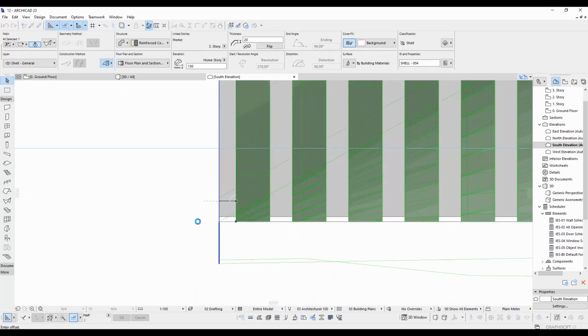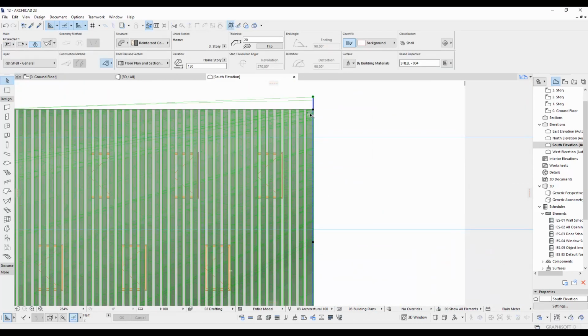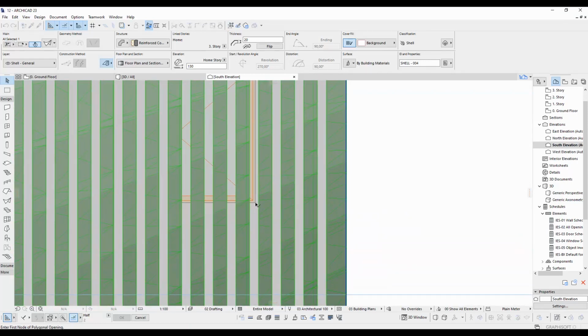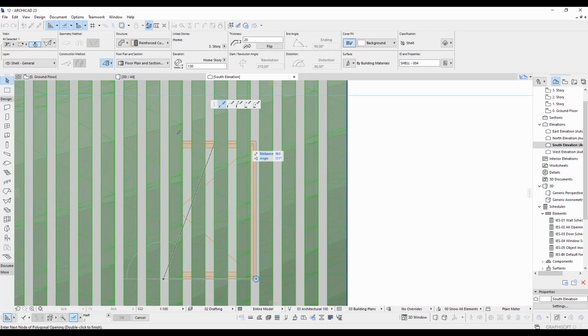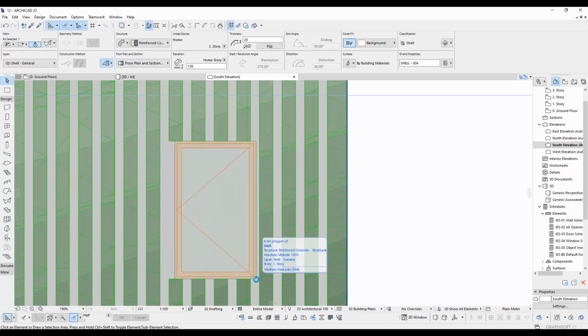I'm just going to make window and door openings with the same method. I can use the reference tool for exact matching, but this time it won't make much difference. I first create a rectangle roughly and will offset its edges after that for proper matching.